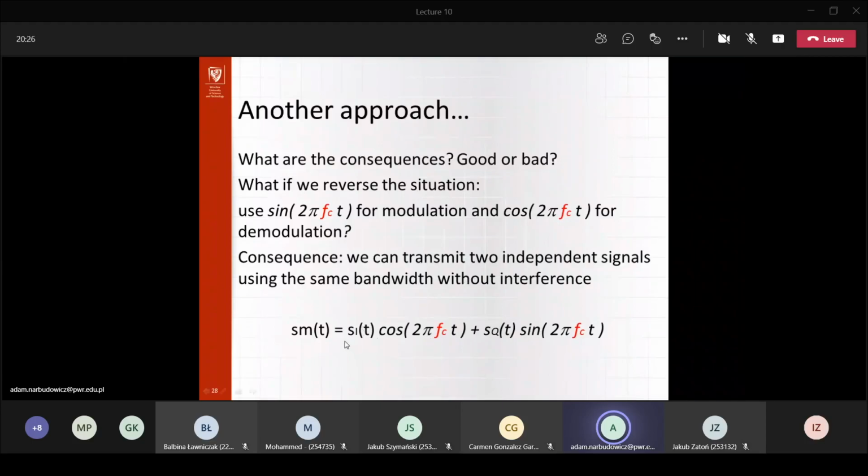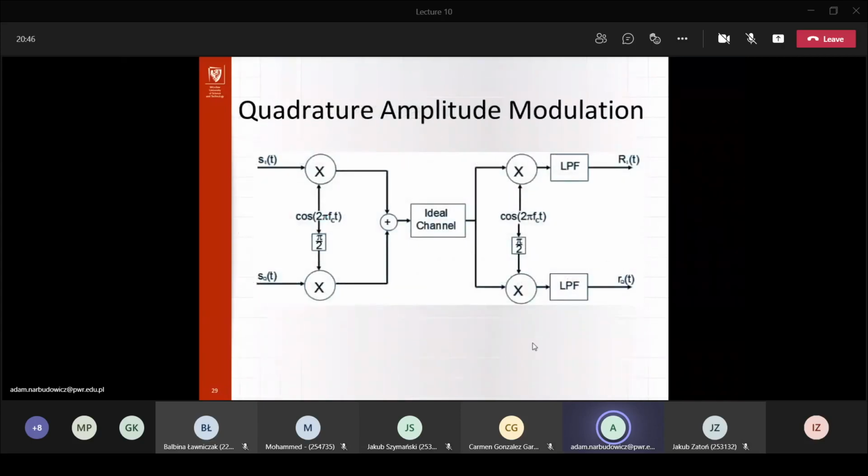That we have here as the in-phase component, modulated by cosine of 2 pi carrier frequency, plus another stream signal Q. So that's our in-quadrature component in the baseband, multiplied by the sine function. And we then end up with this, which is a standard diagram for most of the quadrature amplitude modulation. So in the second slide, we're discussing QAM more or less as combining amplitude and phase.